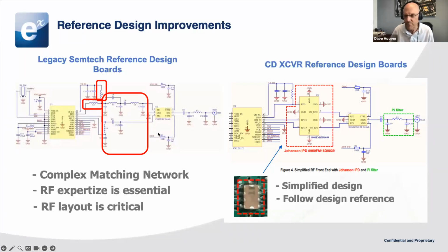So the legacy reference design, all of this is RF matching componentry, right? So this is how do you tune for particular frequencies? How do you tune for a particular antenna? All this stuff, I think if you count the components, are right around 10 passive components that need to be put into the design. And again, remember, all this is kind of spread across the legacy reference design's Arduino Uno footprint, which is pretty large at the end of the day.